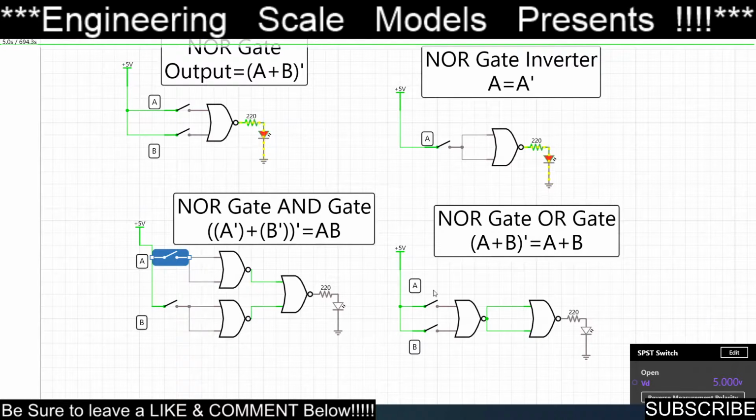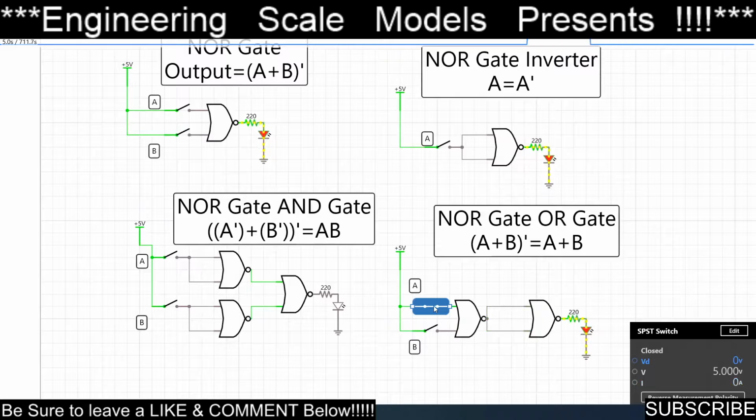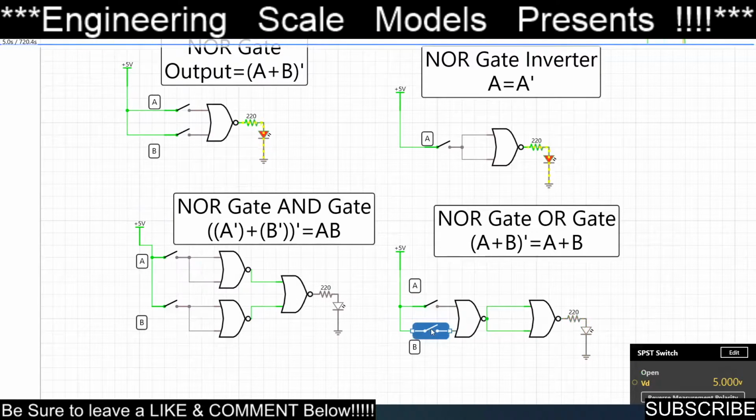Now if you wanted an OR gate, you just need two NOR gates, and you connect input A and B to the first, and then that output goes to both inputs on the second one. And as you can see, the LED is off. 5 volts to this one, 5 volts to this one, and then at both of them, there you go. So this is how universal the NOR gate is.